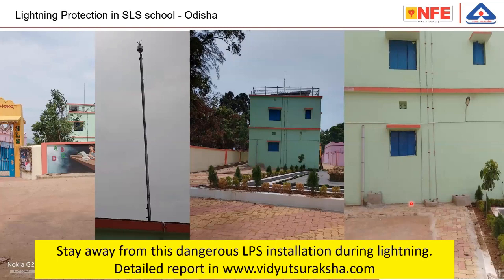This is completely a violation of these standards. The violation is not only on the down conductor and the earthing, the violation is also on the air termination system. One of our volunteers from NFE went to this particular school and he had a talk with some of the villagers. The villagers are under the impression that this rod, where I'm moving the cursor, is going to protect not only the school building, but about 117 meters all around the school. So this rod is installed and a story has been given to the villagers that the whole area is protected, which is also a non-standard installation or a non-standard theory.